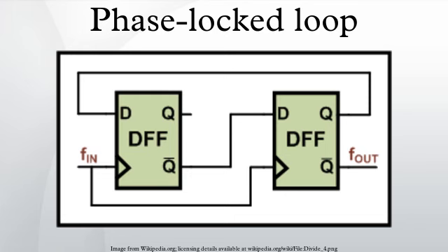A bang-bang charge pump phase detector must always have a dead band where the phases of inputs are close enough that the detector detects no phase error. For this reason, bang-bang phase detectors are associated with significant minimum peak-to-peak jitter, because of drift within the dead band. However, these types, having outputs consisting of very narrow pulses at lock, are very useful for applications requiring very low VCO spurious outputs. The narrow pulses contain very little energy and are easy to filter out of the VCO control voltage. This results in low VCO control line ripple and therefore low FM sidebands on the VCO.